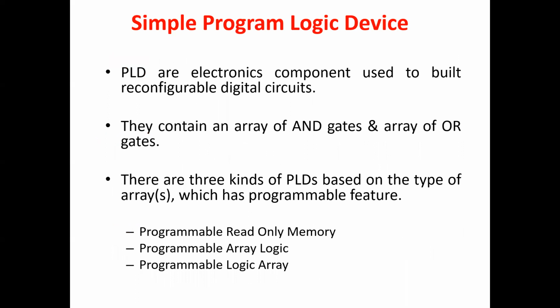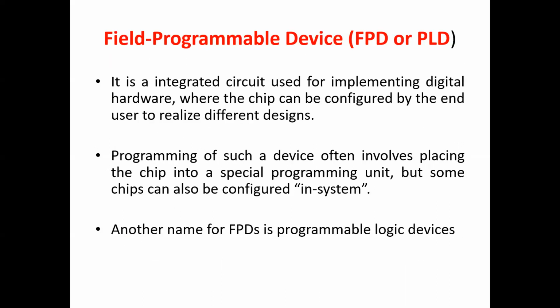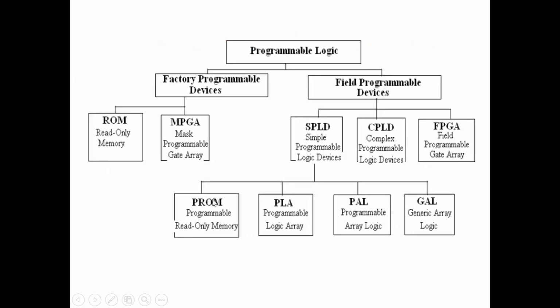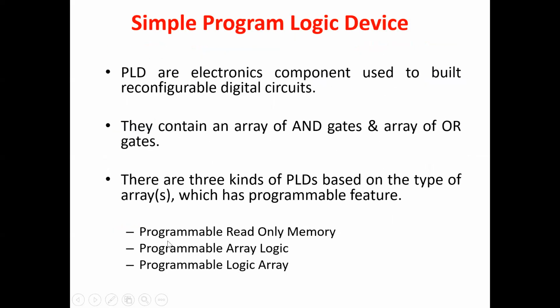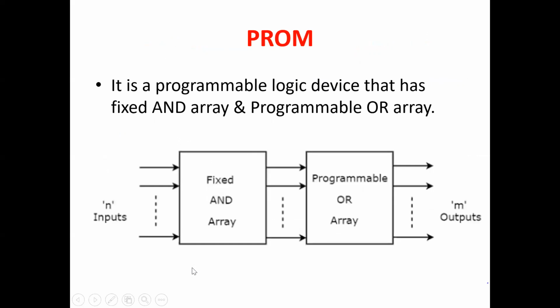Coming to simple programmable logic devices, under this you have the PROM, PLA and PAL. So what do you have? Again three kinds: programmable read-only memory, programmable array logic and programmable logic array. What is this programmable read-only memory? It has a fixed AND array and a programmable OR array.